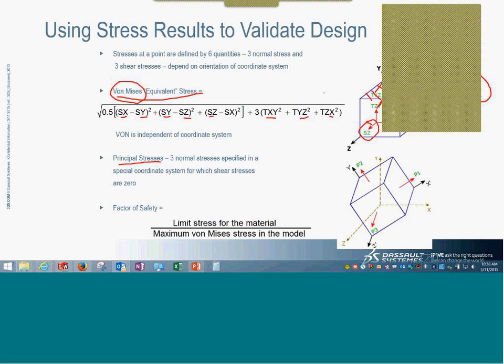The way it solves is like, if you have any FEM book, you should be able to explain it. It is a simple, straightforward matrix where it is just inverting the stiffness matrix known from the geometry and it will extract the strains. In case of the Intel solver, I would say it is more of a solver which is optimized for machines which are using an Intel processor.